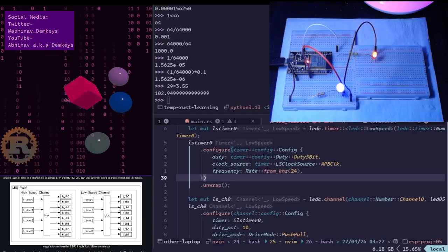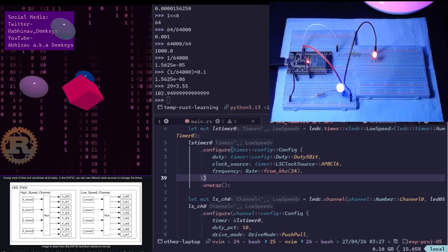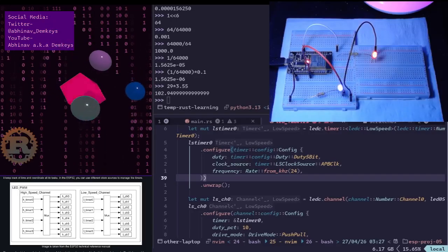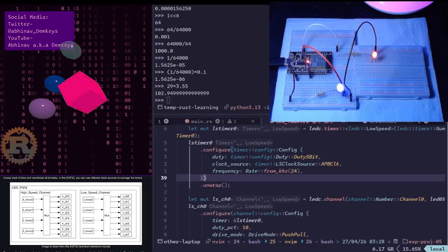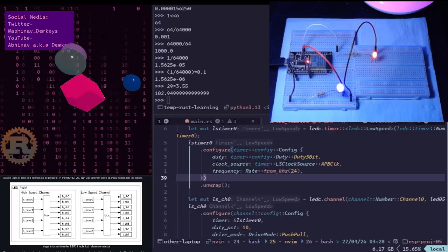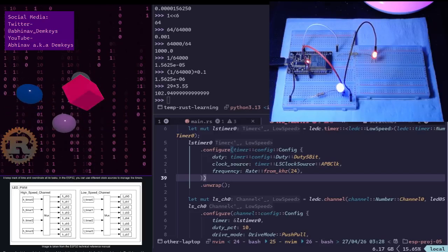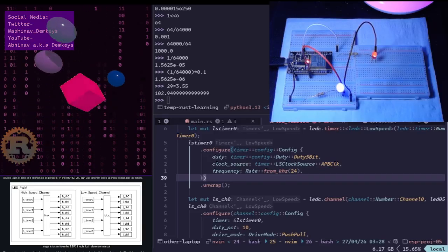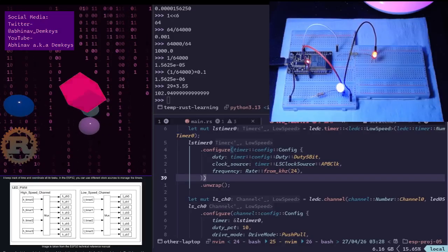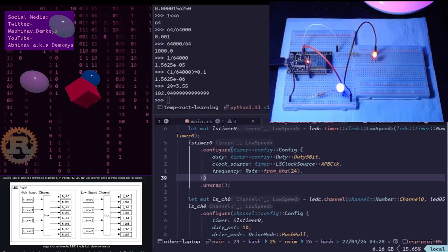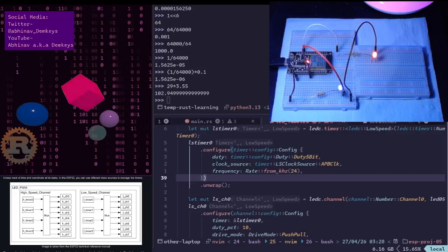The CPU can be turned off, and you can just use the PWM hardware. Apparently, you can also turn off the PLL, and all of this can be very helpful in terms of conserving power. Mainly I'm worried about conserving power, so that's my main reason for doing it.